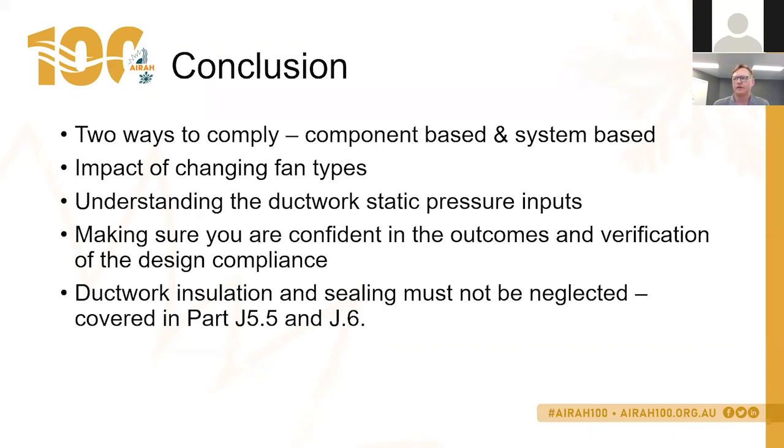Make sure you're confident in the outcomes and verification of your design, because as we've noticed here at the moment, the current ABCB calculator has some slight errors in it. It's only a minor error, but you need to be very confident that your assessment is going to meet compliance. And then also don't forget about ductwork insulation and ductwork sealing for parts J5.5 and J5.6. That's the conclusion of the slides.